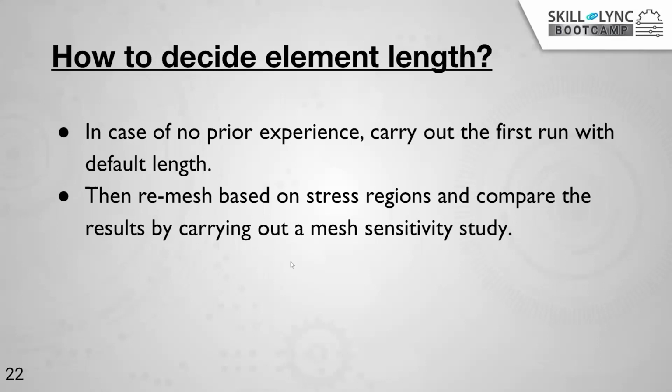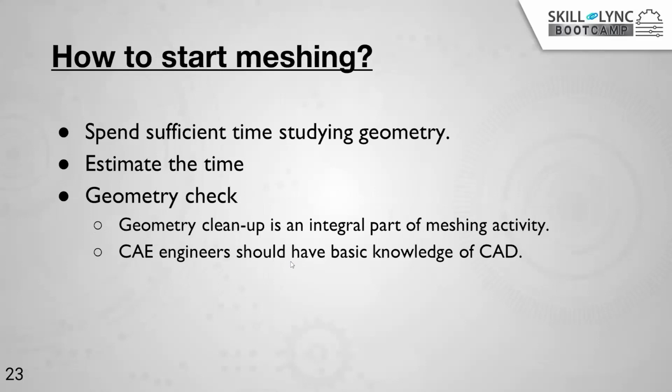Now, how to start meshing? Before you start, don't just randomly or abruptly start the meshing operation. First study the geometry, discuss with the design engineer or product engineer, understand the requirements, the problem, and their expectations. After that, you estimate the time based on the requirements and your competency. You estimate the timeline. Only after that do you start with the geometry check, before starting the geometry cleanup.